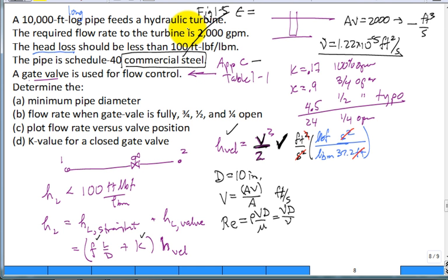All right? And so I have to do that myself. So for commercial steel, 0.00015. What are the units on that? Feet. You're absolutely correct. They're in units of feet. Very good. So all those numbers are not labeled. You just have to know, oh, it's feet.